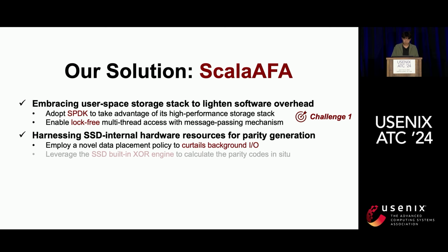In response to the CPU burden imposed by background conversion, ScalaAFA proposes to offload these tasks to SSDs, thereby leveraging the SSD built-in XOR engine to generate parity, to mitigate host and SSD communication overhead in the offloading. ScalaAFA takes a novel data placement policy that enables transparent data gathering and in-place parity computation.